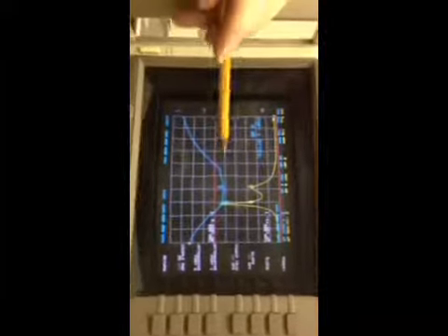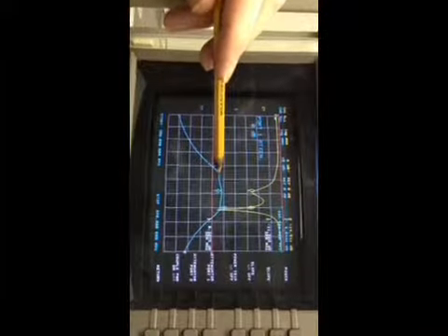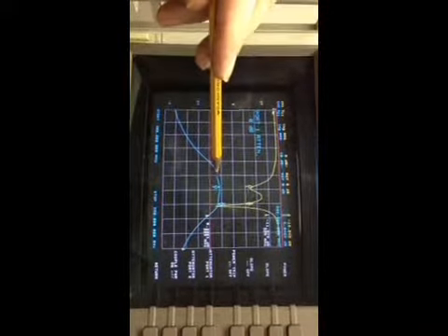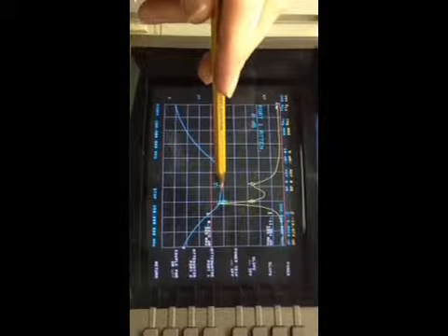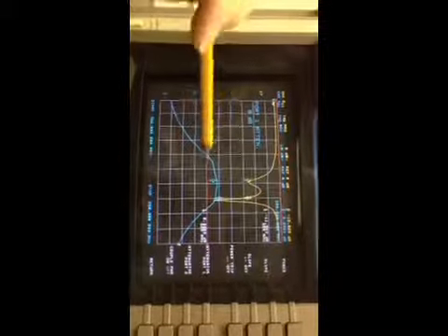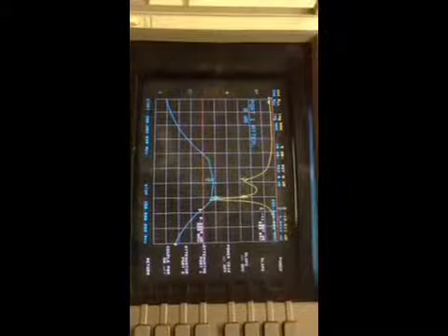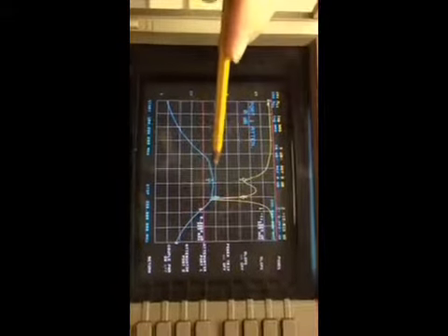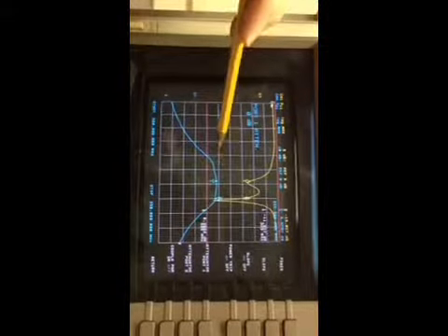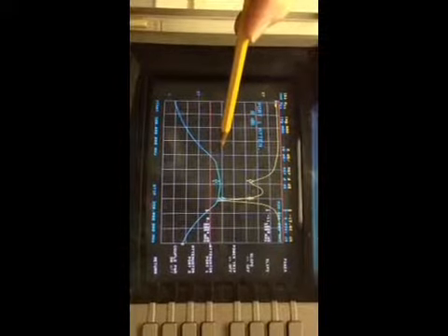Looking at the network analyzer, we can see there's point 1, which is the start of our frequency at 329 megahertz, and point 2 is the end of our frequency at 335. Realistically, it's pretty flat for an RF filter. You can see that we're letting in quite a bit of extra space over here, but really that doesn't matter